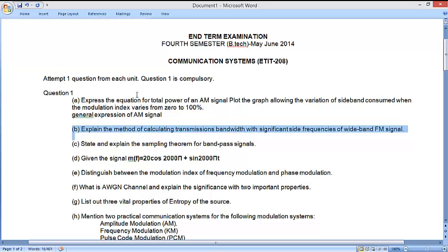So we represent the Carson rule by B is equal to 2 delta F plus 2 FM, okay, where FM can also be treated as 2 delta F divided by beta. Now here delta F is frequency deviation and beta is the modulation index and FM is the modulating frequency. And also you have to consider the case of pure wideband.